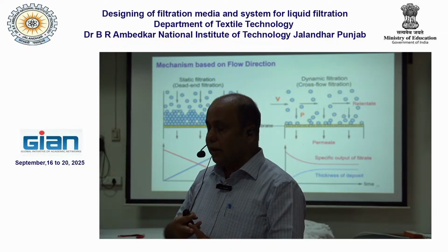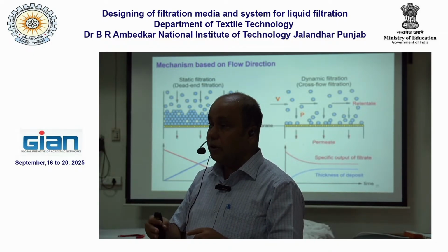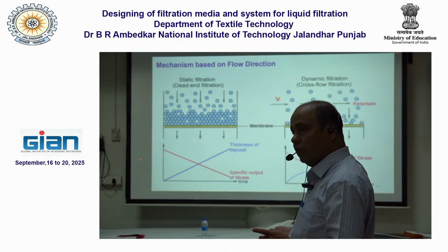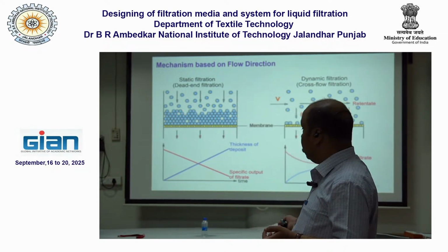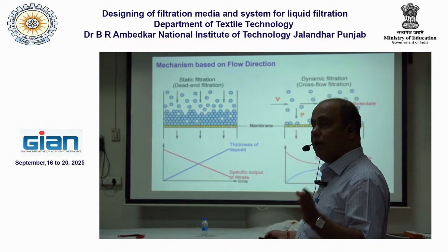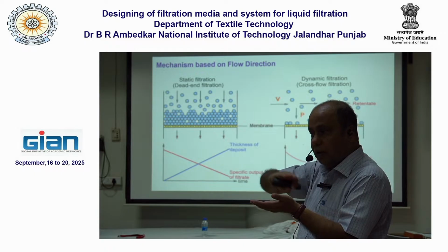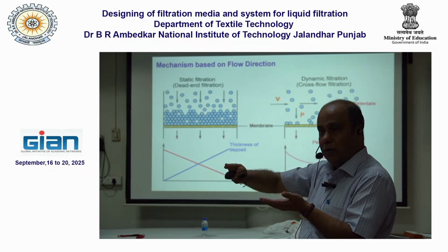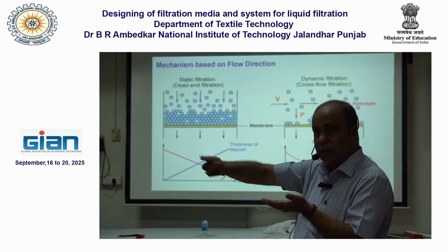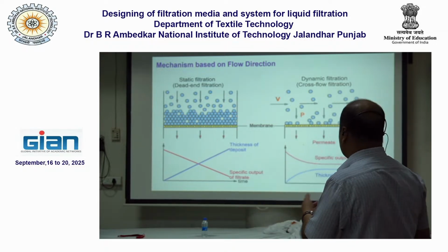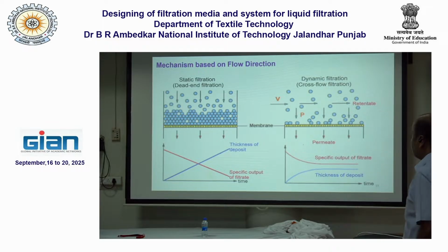So in that case you can go for cross flow filtration without cake formation. In this case cake formation is possible, without cake is also possible. In this case there is no possibility of cake formation, because it will be completely sheared out all the time. Because of the fluid flow, the cake cannot form, it will shear, okay, because it is flowing in the plane. So proper cake formation is not possible in the case of cross flow filtration.